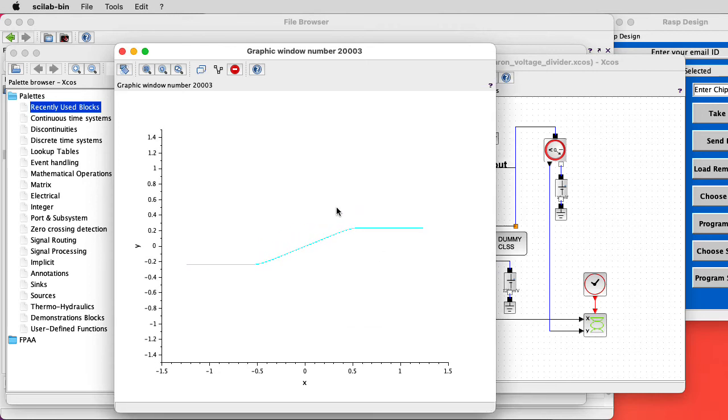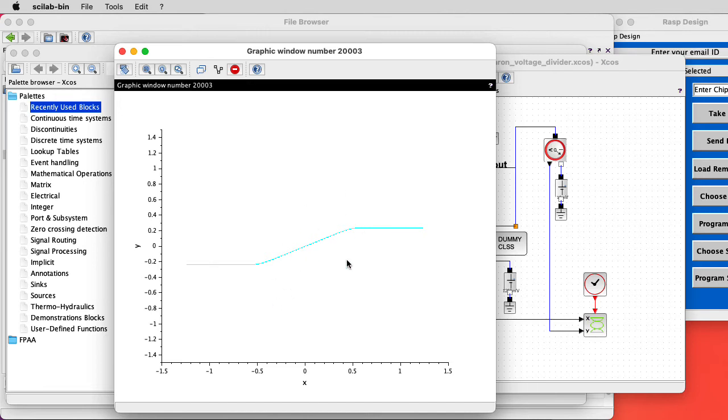Look at this. So we have this nice linear region in the middle here, as we would expect from our voltage divider. Now, OTAs are not linear devices. When you start to push them to their extremes, they have this hyperbolic tangent kind of nonlinearity. That's true for BJT-based OTAs, like we're used to in most synthesizer designs, and also in MOSFET-based OTAs, like in these FPAAs.